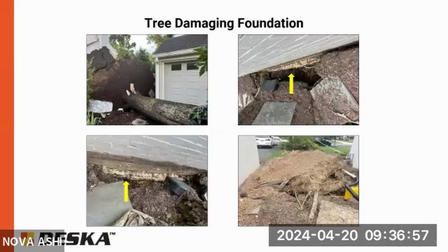Yeah, so in this particular area, probably 95+% of the slabs are not structural. Now, I wouldn't just go into every home inspection thinking that, but I'd be aware of that. If you have a lot of cracks in the foundation slab, I would probably be a little bit more careful at other areas. You see cracking in other places, maybe the slab is structural.